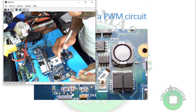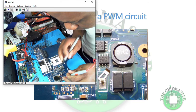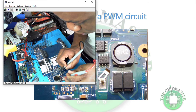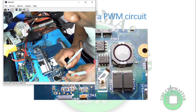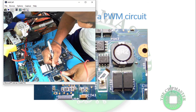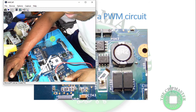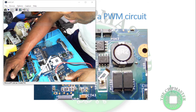I'll connect my red probe to ground, and I'm going to connect the black probe to the first pin. If it beeps, then this is the source pin. This is a lower MOSFET. See, pin number 1, pin number 2, pin number 3, and pin number 4, which is the gate. There's no beep. If there's a beep, that's a short circuit. So pins 1, 2, 3. This is the drain, which is connected to the coil. See, it's connected to the coil. Let me zoom in. Let me see if I can zoom in.